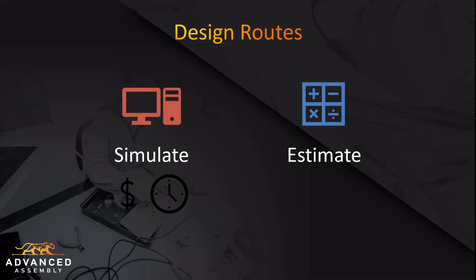Most modern design and CAM software platforms can run a conductor simulation for impedance values, either by Gerber layer or stack up. Typically what you can do, if you design a Gerber layer and there's a certain trace thickness, copper weight that you put in, you can essentially highlight that specific trace, that specific net, and run a simulation test on how that is going to perform.